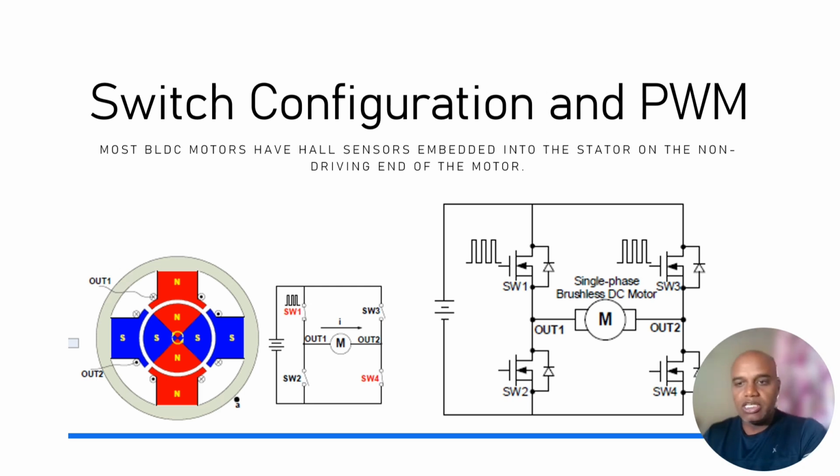However, we always keep in mind that the BLDC motor is not an AC motor, it is a DC motor. It runs on DC. The only thing abbreviated as single phase and three phase is related to the windings. If we have three windings over the stator, placed 120 degrees apart mechanically, then it is known as a three-phase BLDC motor. And if we have only a single-phase winding, then it can be called a single-phase BLDC motor.